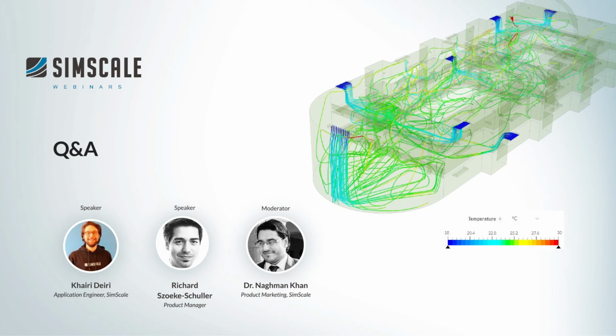Basically, we have a file format connection via an OBJ file, so we can export from there to an OBJ. I don't know, meanwhile, it might even be possible with STL. And then you upload the STL to SimScale and run your wind comfort studies, for example. That's what we used in that case, but you can also use it for indoor studies as well.